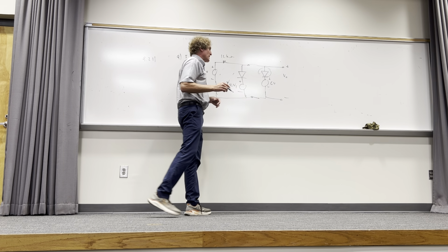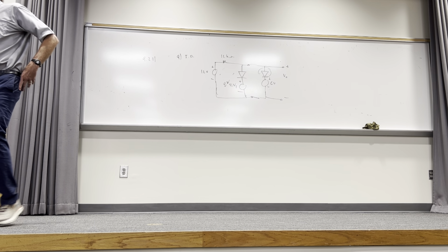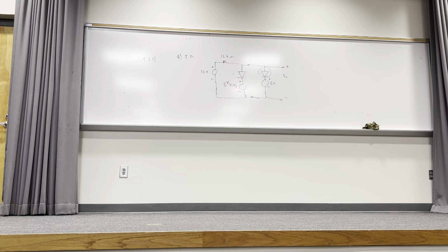I want you to think it through. Some people probably see this. What did I just do effectively? I put the larger potential voltage in series with the first diode. The second diode only has 6 volts to overcome. That diode has 8 volts. What do you think is going to happen? Your gut feel. What's going to be the output voltage? How many think it's 6?